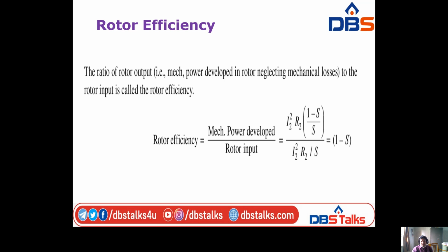Production of rotating magnetic field. How much magnetic field is produced in different situations? That is, at omega t equal to 0, omega t equal to 60 degrees, omega t equal to 120, omega t equal to 180. At any instant of time, the magnitude of the RMF is the same. That is 3 by 2 phi m, that is 1.5 phi m. Right? By using vector diagrams, you can derive it easily at every instant of time.